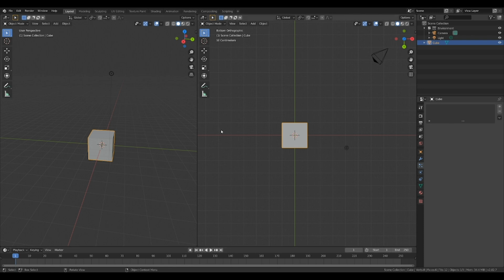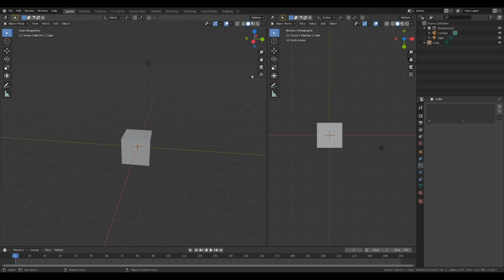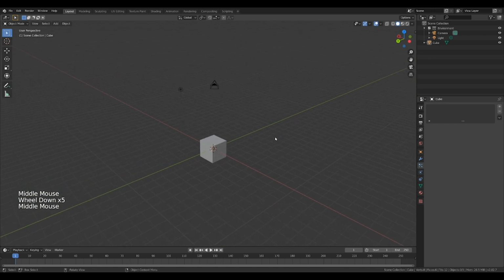Now let's say I don't need this window anymore, how to close it, and this is really not intuitive, but it's really good to explain. You just do the same thing you would do to create a new window, so click on the crevice, but then you drag backwards. Ooh, that was not it. Let's try again. Click on the window, there we go. And then drag it towards where you want to collapse. So you see the little gray arrow now? So I'm collapsing this one. And one more time. There we go, back to our normal viewport.